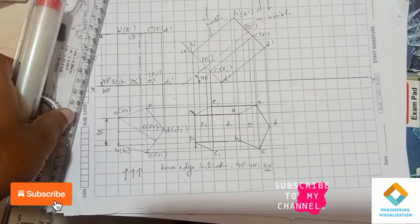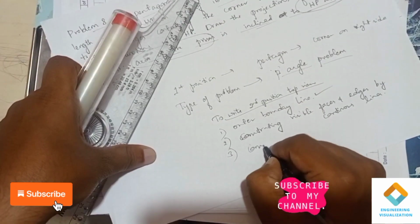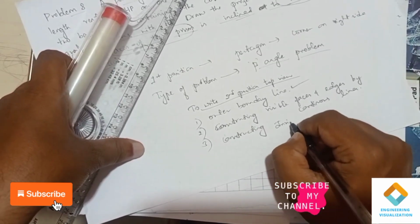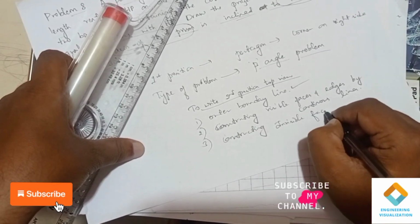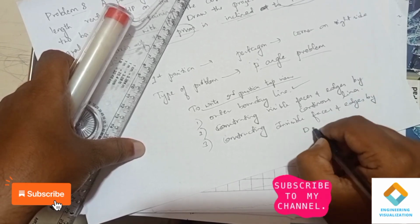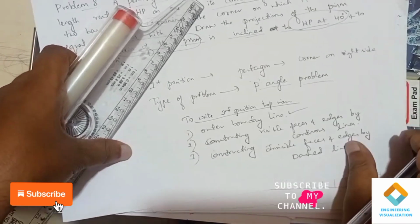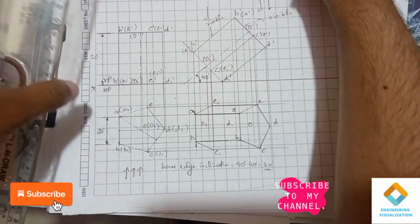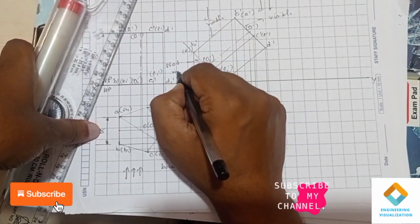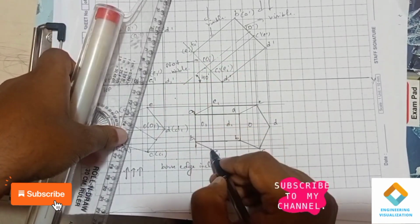Now the third step is writing the hidden faces. So constructing the hidden, or you can say invisible, faces and edges by dashed lines here. We need to use the dashed lines. You can see here the bottom face of this pentagonal prism is not visible, but already a part of the pentagon we have written with a continuous line.